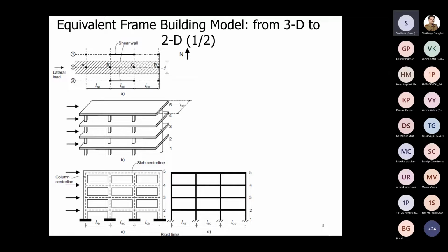Let's say we have reinforced concrete columns and a slab system. If the slab is there, that slab is also modeled as a beam. Or maybe there is a beam at the location of the columns, but there is also a slab. So we need to model not only a beam, but also a slab portion, and that is the so-called beam slab element.